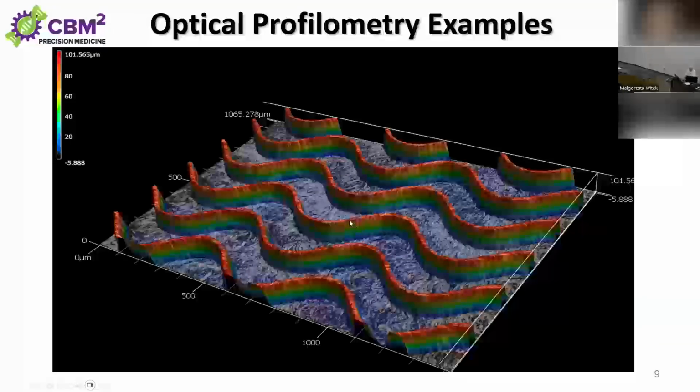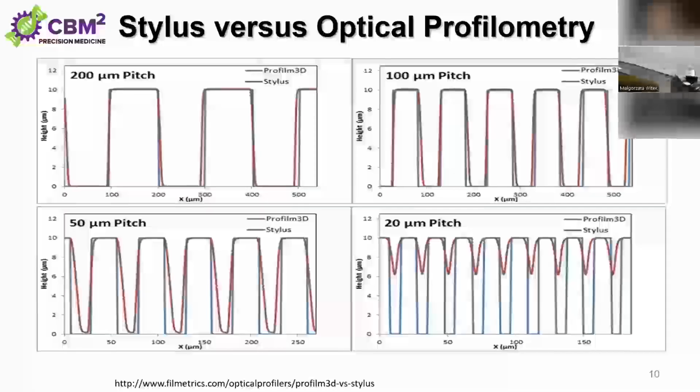So you can see this right here. They're about 150 microns deep and 25 microns wide. And this is a pretty image to look at. This is not using fluorescence. It's using scattered light that's reflected back off of that surface and measured by this detector within this confocal microscope. And what's really nice about this is that it's not limited by the size of the stylus or the tip of that stylus that runs over the surface. And there's no contact. It's just photons impinging upon that surface.